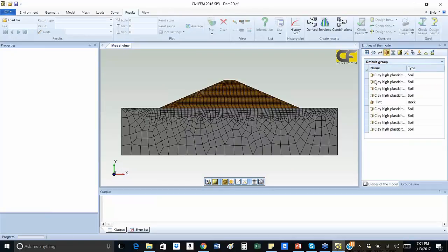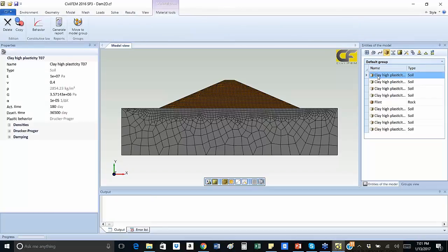Now we see two types of materials, and notice the density of the mesh is always best to do denser at the interface, as is the case here. The soil itself doesn't need to be that refined away from the surface, in keeping with the same Saint-Venant's principle of load application distance from boundaries.